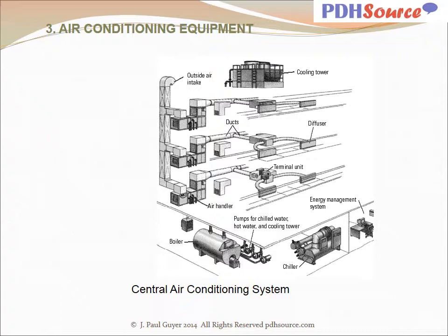And then the return air would be returned. It could be in one configuration returned in a return air duct, or in the illustration here, this system is using what's called the plenum space, which is the space between the suspended ceiling in the office space, we'll say, and the floor deck above. And the return air is pushed in after it has heated the occupied space.